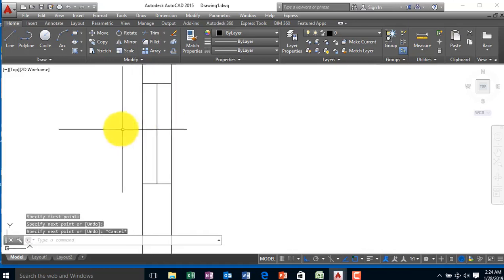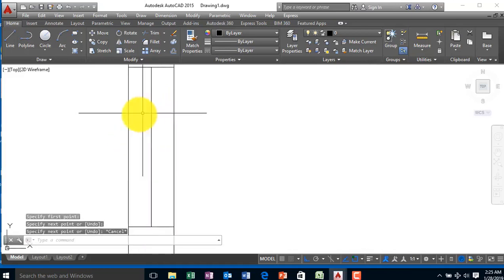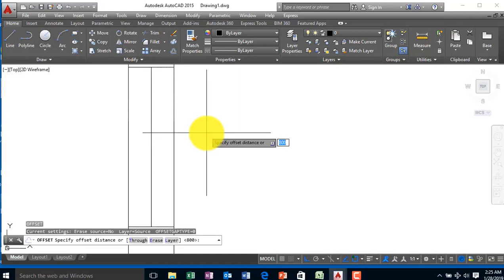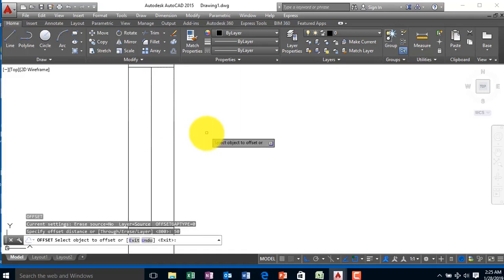Have this. So we know that we still have to make it look more like a window, maybe a sliding window. There are different types of window. If you go back and check your architectural textbooks, you see the different symbols, how you'll be able to represent them in plans. So for this, let's quickly show that it's a sliding window. Best of my knowledge, you do something like this. You offset, you have a 50 mm.